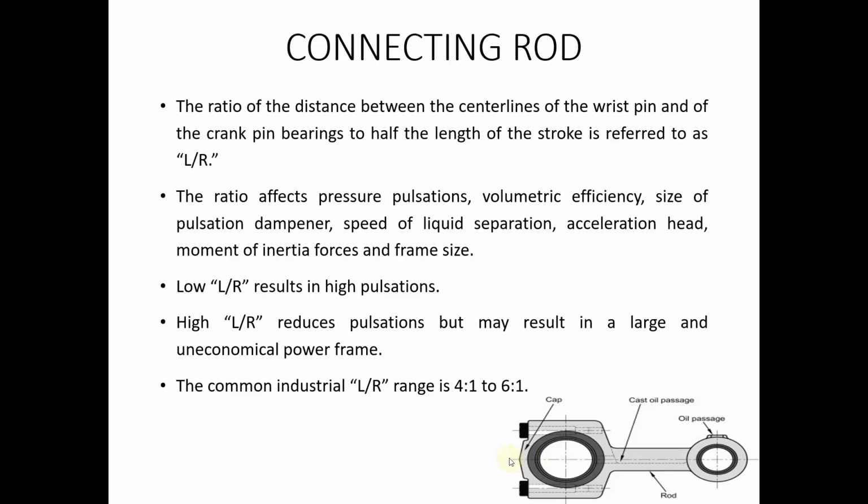These holes will ensure the passage of oil from the reservoir up to the area where the pistons are located, and it provides lubrication. This is one arrangement. There are also other arrangements where the holes are drilled at the sides. So there are different arrangements of connecting rods.